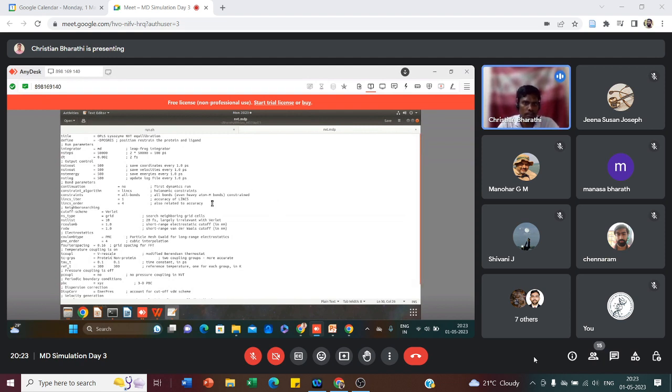This is the parameter file for NVT equilibration. We are using the MD integrator. It is the leapfrog integrator. I already told you, we are solving Newton's equation to calculate force, momentum, position, velocity, and other things from our input file. That is taken care of by the MD integrator. And steps are important for running equilibration and MD.